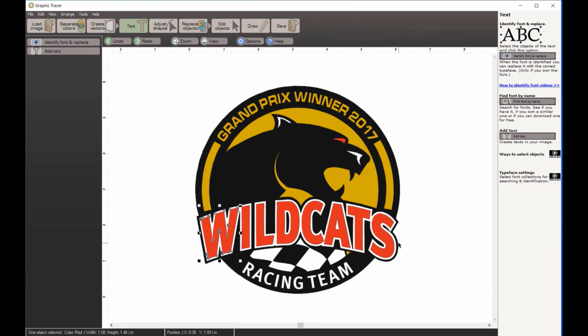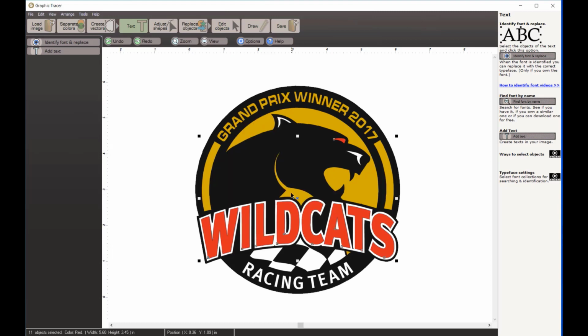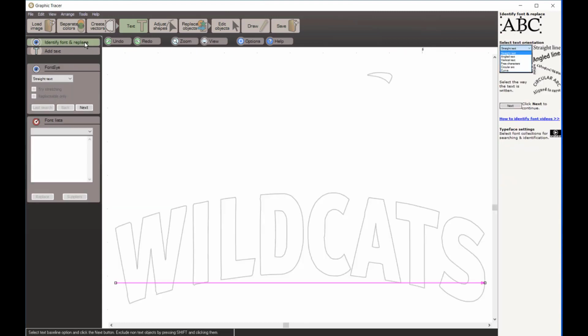Now I'm going to search for the Wildcats. I could marquee around that, or I could choose a letter. If I right click my mouse with that first letter selected, I can select same color. Graphic Tracer will go through and select all of that same color in that graphic. When I come over here to identify and replace, you can see I've got the Wildcat selected, but I also have that eye selected. So I'm going to hold my shift key down, click on that, and deselect that eye. If I left that eye up there, it would throw off my font search. I want to have only the letters that I'm searching for as a part of this search.